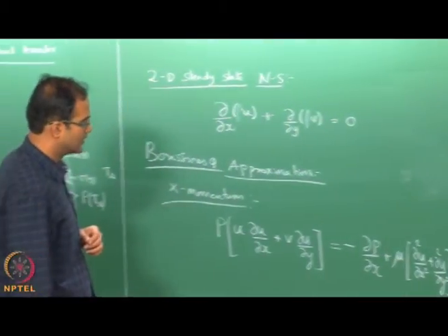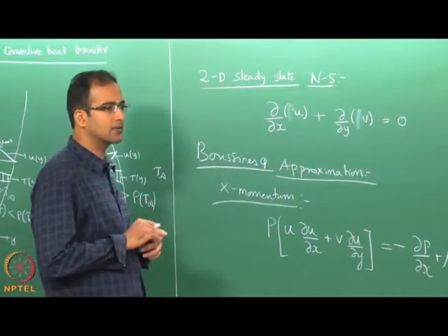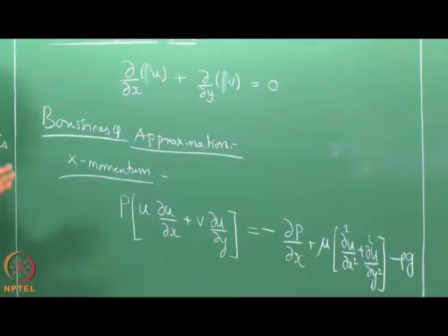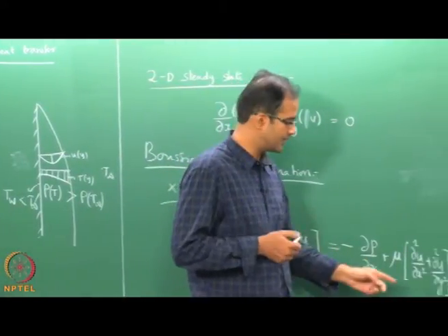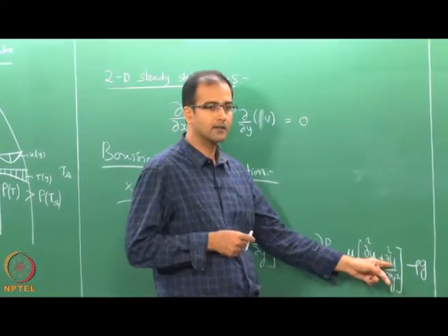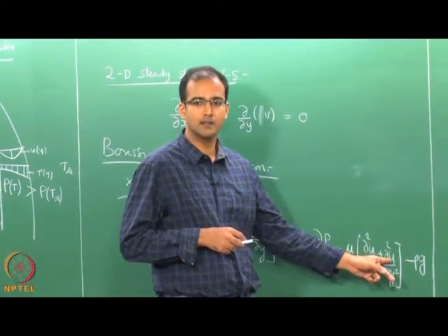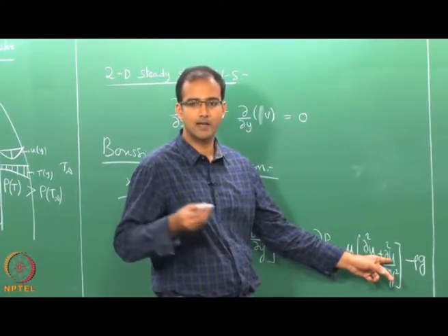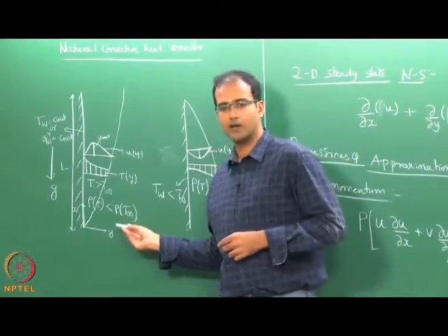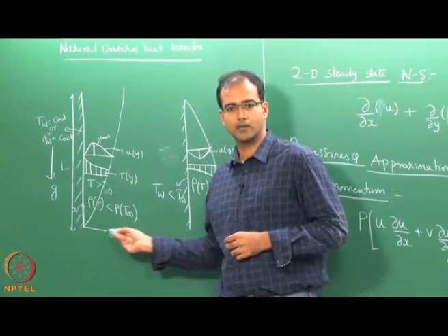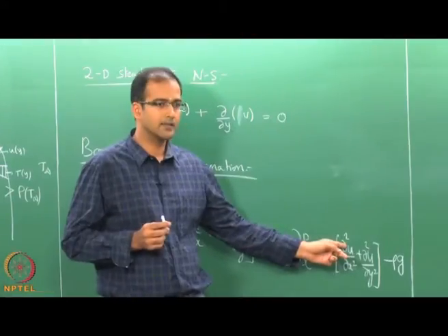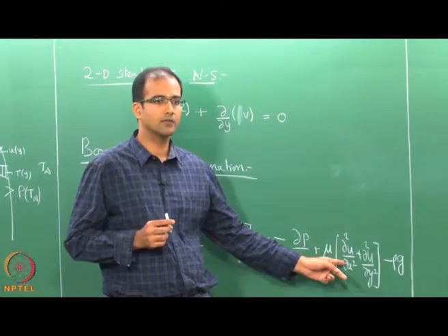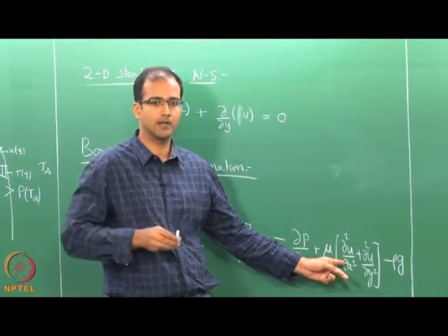Now once again, similar to the external forced convective boundary layer, if we do a scaling analysis, or an order of magnitude analysis, we can show that the diffusion in the y direction, the y direction being the horizontal direction now, Cartesian x, Cartesian y, is much greater than the diffusion along the length of the plate.